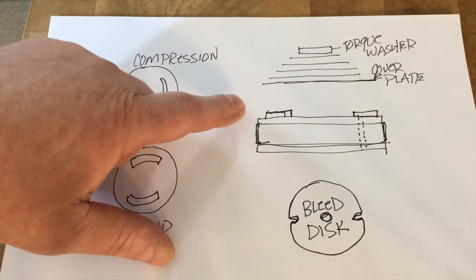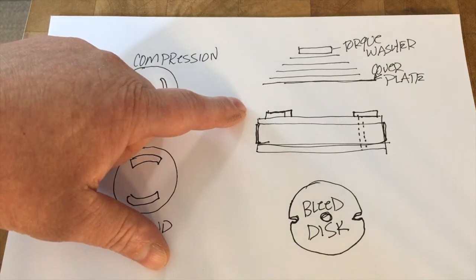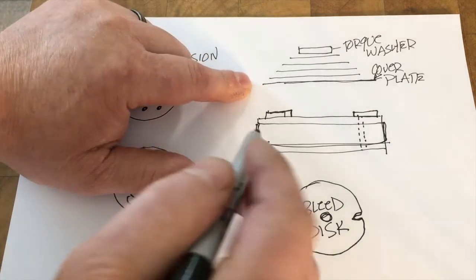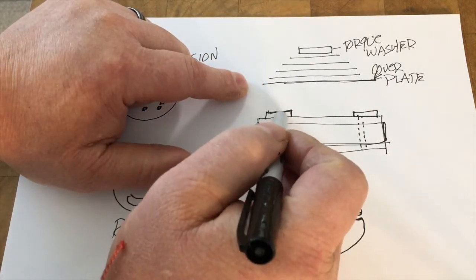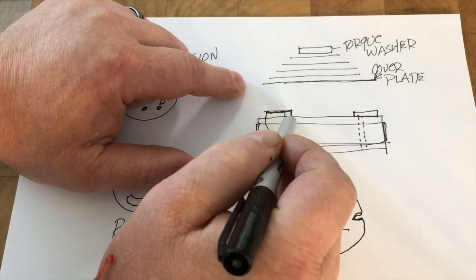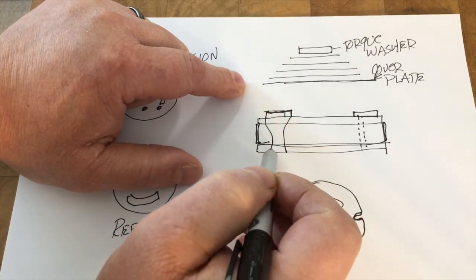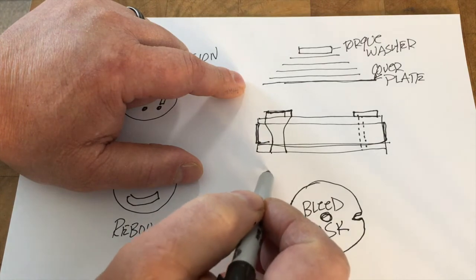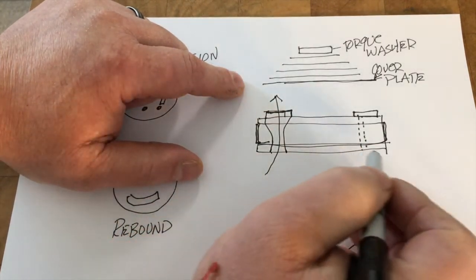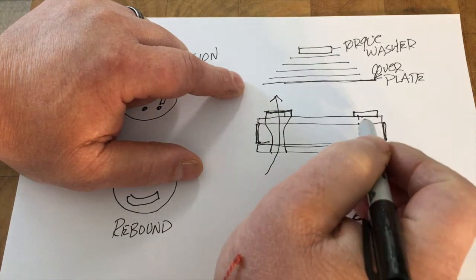Your typical valve stack, like I said in the other video, is basically like this. The bottom plate will go right up against the piston, and these are the orifices, let's say, that will go through your piston and to the other side. So oil will flow through here and hit your cover plate, both sides, I guess.